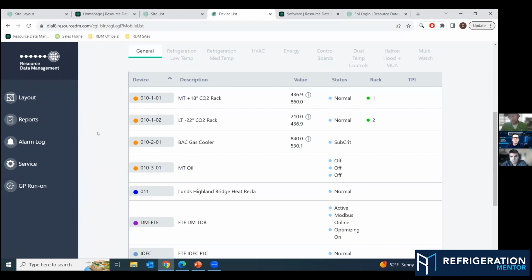Because, guys, I've turned cases all the way up to 15 to 18 degrees on the set point on the controller that actually equaled 8 degrees. So you have to pay attention to stuff like that too. Just because a controller says that's what it is doesn't mean that's what it is. You have to check this stuff, and there's a lot more checking with all these controls and sensors and temperature probes. And I like what you brought up there.